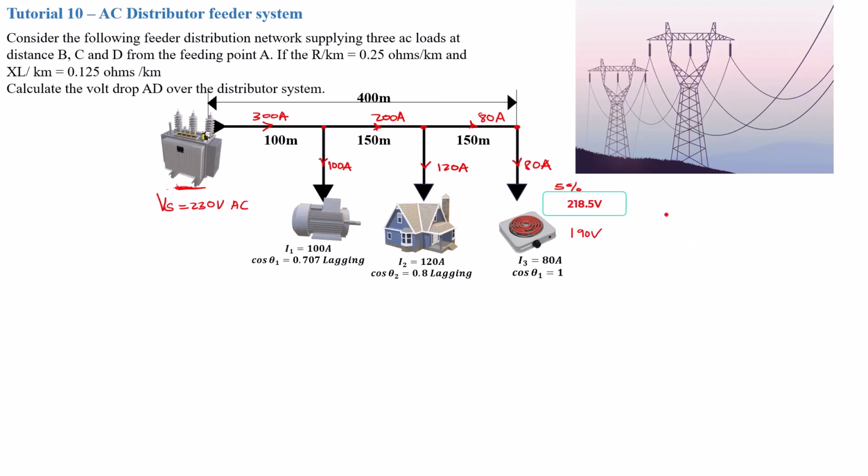So to remedy that, many households make use of what is known as a voltage stabilizer. It is basically a device with a transformer that takes your input voltage coming with all sorts of variation from the line and stabilizes it to a very solid, let's say, 230 volts. So no matter what happens here, so long as the input is within the accepted range of this equipment, it might have a minimum input of 150 volts, then it will give you 230. If it drops below this 150, then it can't anymore. Well, if you get to that point, remember, you've got more problems to deal with on your line.